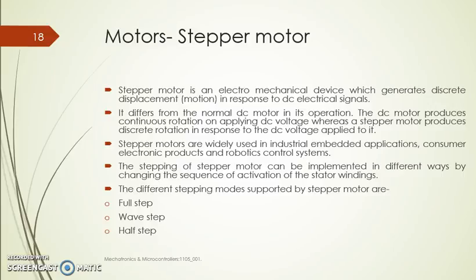Usually, stepper motors are used in embedded applications, consumer electronic products, robotics, control systems, and so on. We can implement the stepping action in the stepper motor in different ways. It is usually done by changing the sequence of activation of the stator windings.